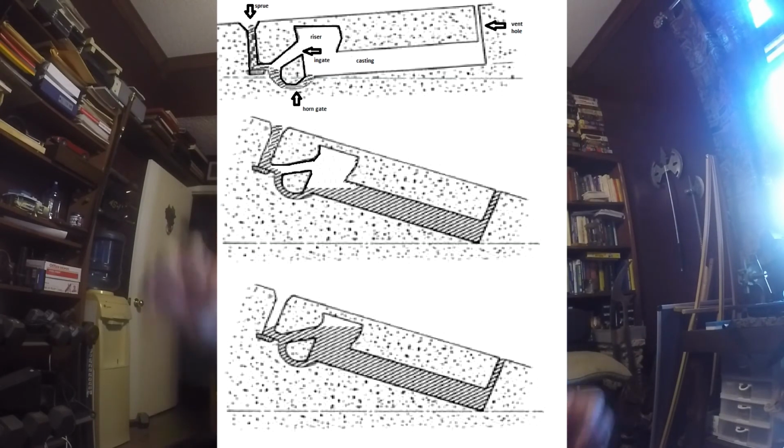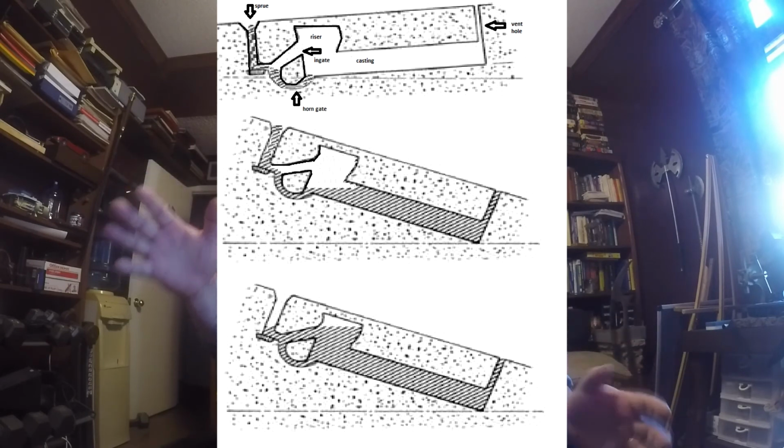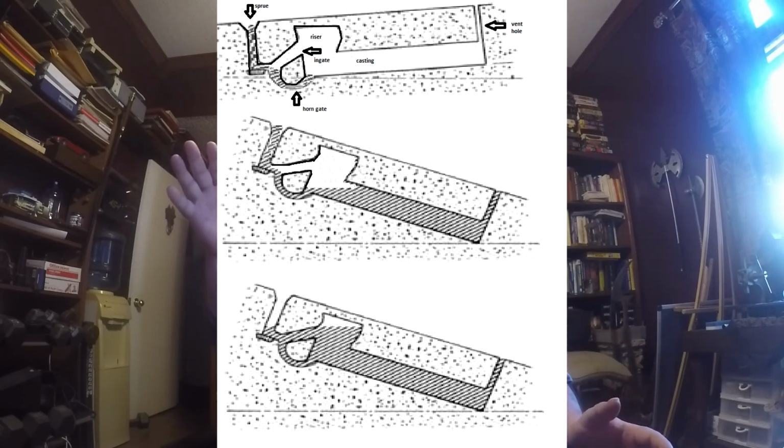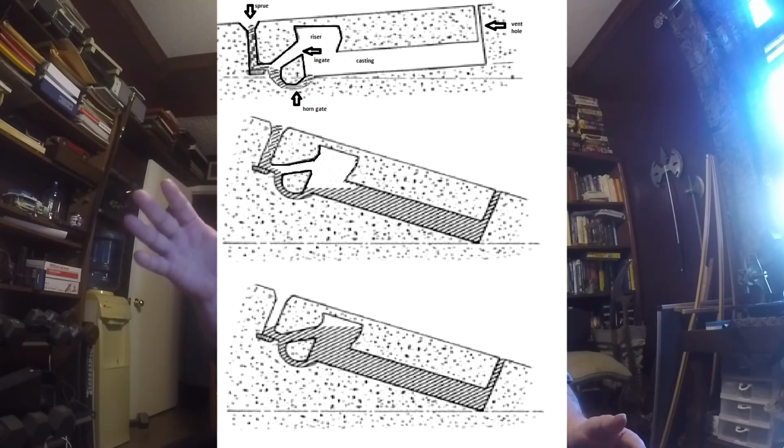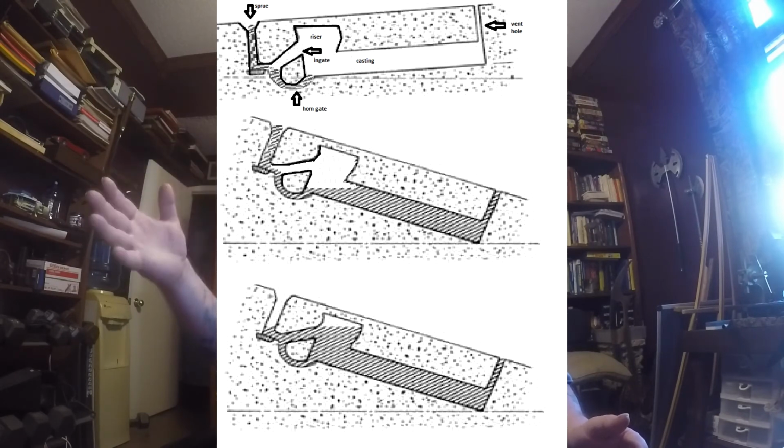Now, this next picture is an example of mold manipulation. You want to affect the directional solidification of this casting. If you were just to feed this casting, with the casting being absolutely flat, the odds would be very good that the bottom would start solidifying before the top, and then the top would finally start solidifying, and the ends would solidify.